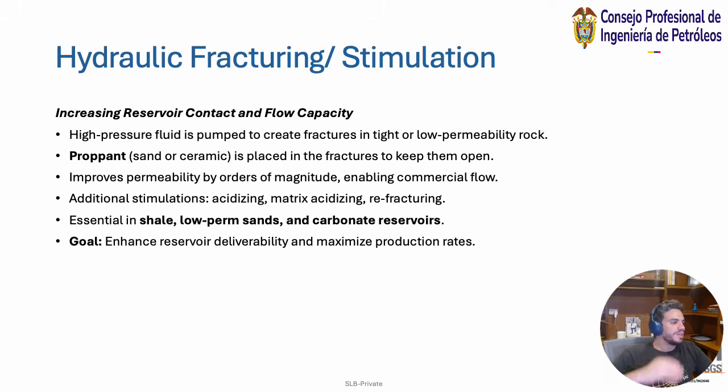So that's what hydraulic fracturing is: you shove this padding down, then you push fluid, then you push proppant. The idea is that you want to increase the permeability of that rock. So again, you're stimulating permeability, and these proppants are placed in the fractures to keep them open. These proppants for oil and gas are very small. They look like small marbles, like your marble toys, but they're usually made of ceramic or sand. You can even push sand.